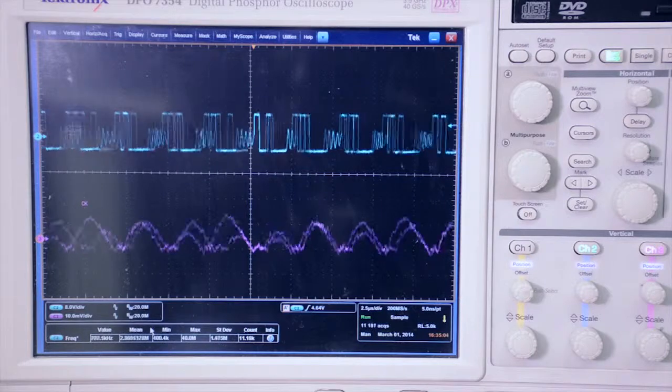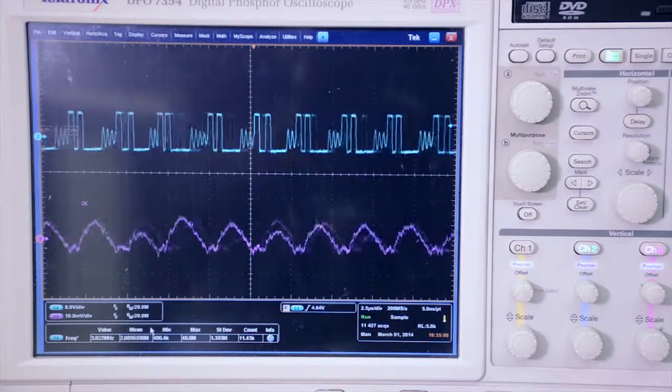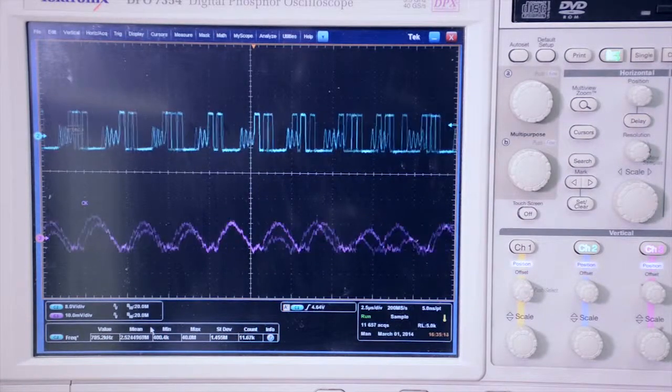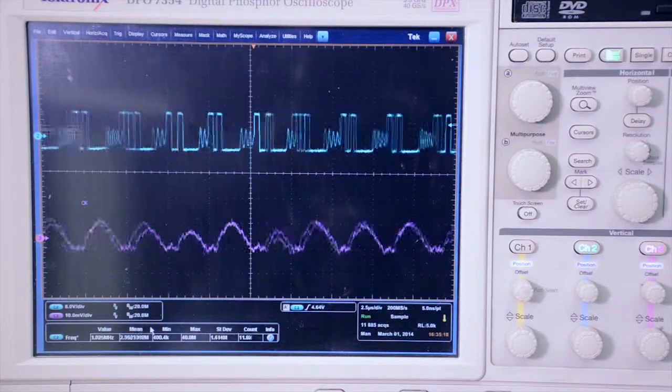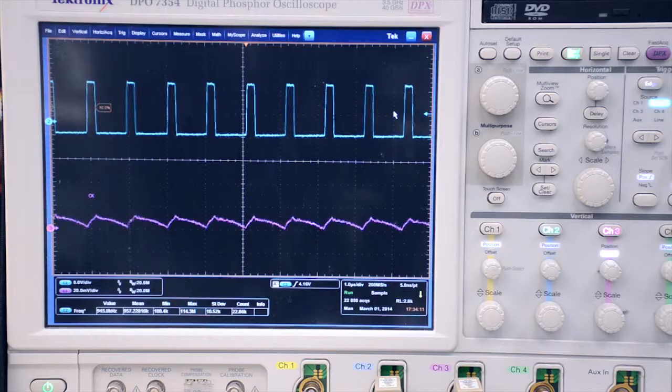This is the experimental waveform based on LM34930 demo board with traditional 10 micro ceramic caps, which has a small ESR around 5 milliohm. We can observe that there is an instability problem, which is predicted from our model as the system has a right half-plane double pole. Now use the customized ESR ceramic caps, which has around 50 milliohm ESR. We can see the circuit is stable, which is predicted from our model as the system now has a left half-plane double pole.